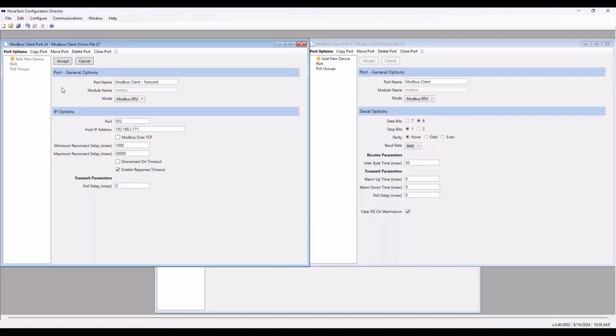When it gets over to the other side, it's in the TCP format. Now, that TCP is not expecting to see a checksum, so it doesn't check the checksum. And when the client sends a message back to the server, it doesn't put a checksum within the Modbus message, again, because the TCP protocol itself includes a checksum. As a result, the serial side doesn't see that. So really, you have kind of two-way failure of the checksum.